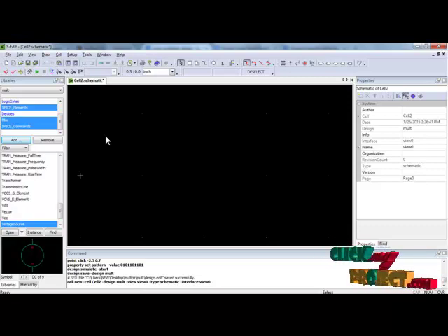After we design in SEdit, while simulating, the circuit design will pass through T-Spice, which we can understand through the netlist generated as SPICE code. Finally, while we are simulating, the timing diagrams will appear in WEdit. Hence, for our CMOS-based designs, we will mostly use these edit tools: again, SEdit, LEdit, WEdit, and T-Spice.